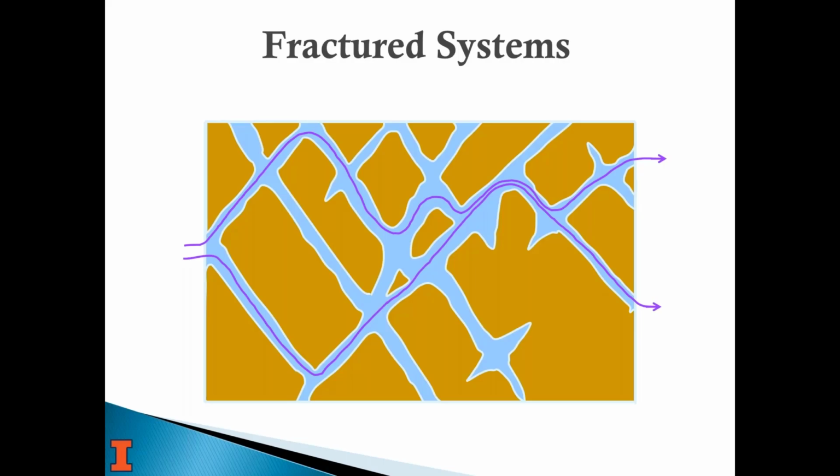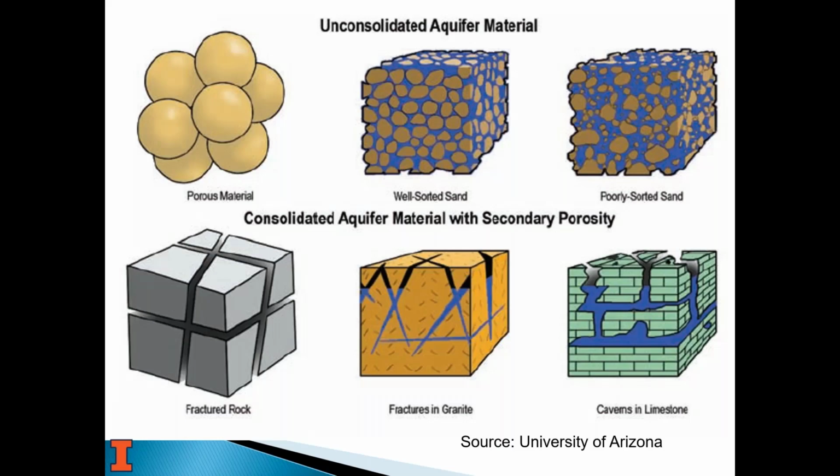But what that means is you don't have a uniform amount of water throughout the aquifer like you do in a sand and gravel system where all the sand's the same, so there's water everywhere. It depends on where you drill your well, how many fractures you hit, and how much water may be available, as well as how interconnected those fractures are. So here's just some examples. I've updated figures for this, and I should have used them because the text is poor.